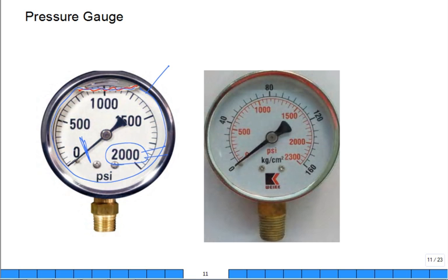What do we have here? We have 2 rings. We have an inner ring of red color showing you unit of PSI, and an outer black ring showing you unit of, hey, our new favorite unit of pressure measurement, kilogram per centimeter squared. Now the PSI, we said 1 ATM is around 15 PSI. 1 kilogram per centimeter squared is around 1 bar. It's around 1 atmosphere. So 1 to 1 for that one. So 1 kilogram force per centimeter squared is right at 1 atmosphere. It's not perfectly on, just like 15 PSI is not perfectly 1 ATM. Okay? But it's close enough.